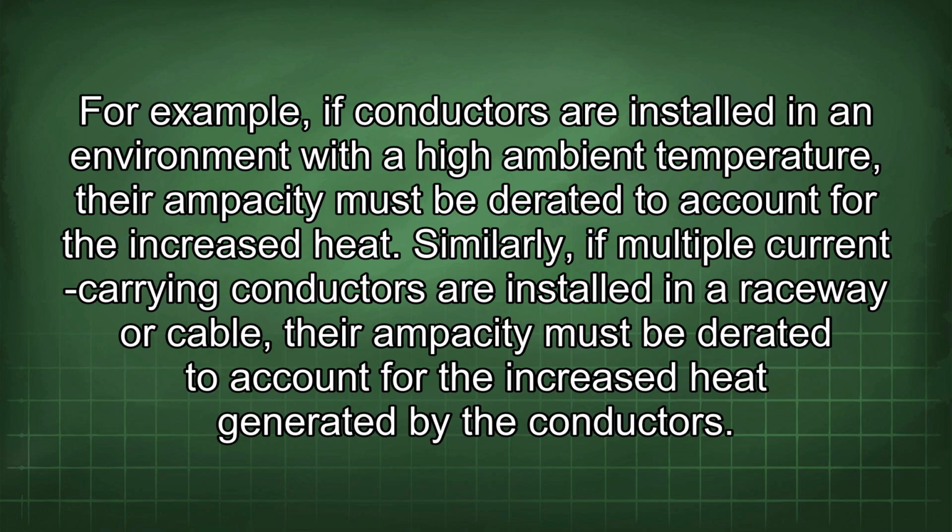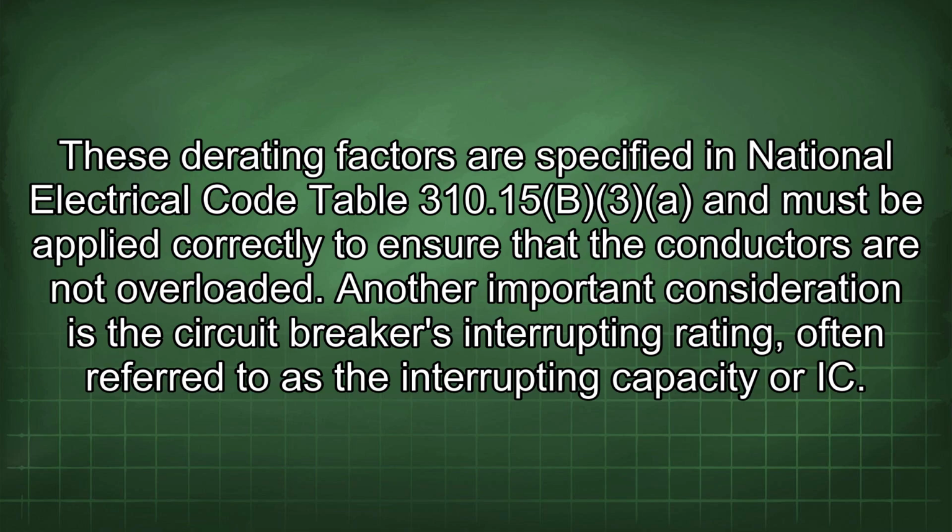Similarly, if multiple current-carrying conductors are installed in a raceway or cable, their ampacity must be derated to account for the increased heat generated by the conductors. These derating factors are specified in National Electrical Code Table 310.15(B)(3) and must be applied correctly to ensure that the conductors are not overloaded.